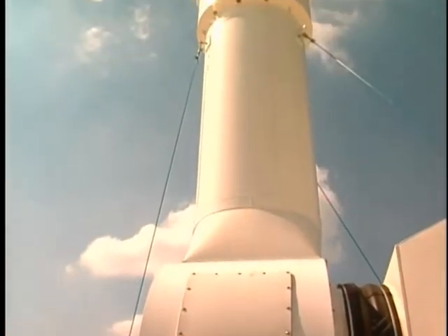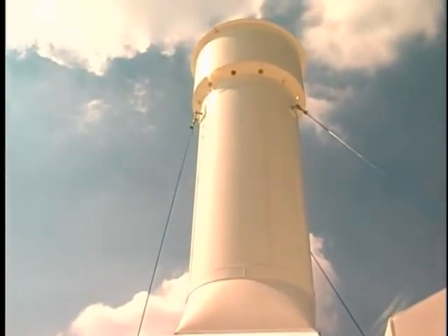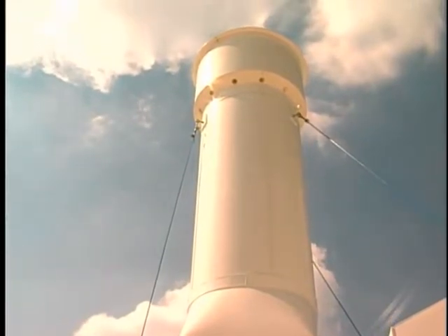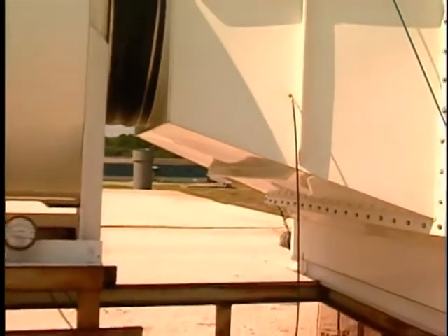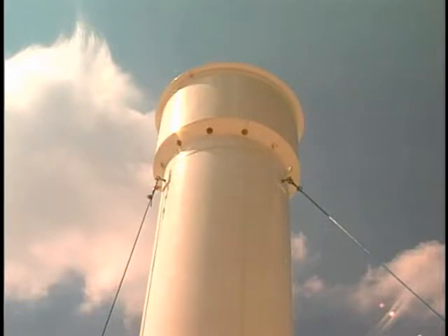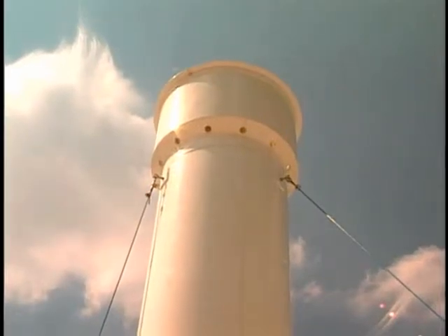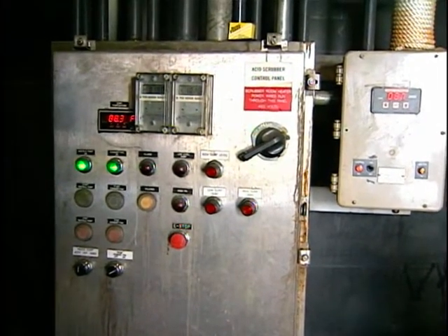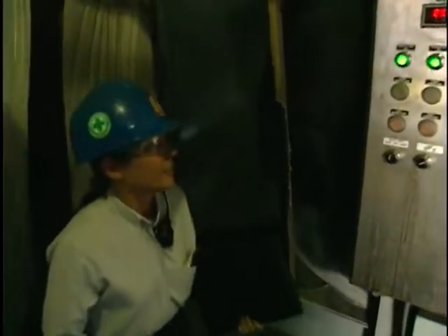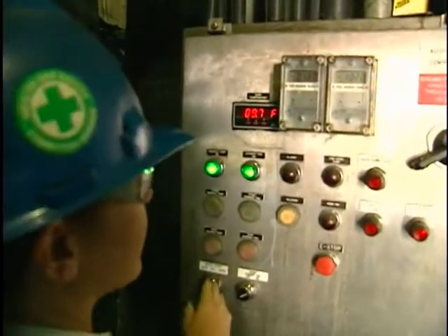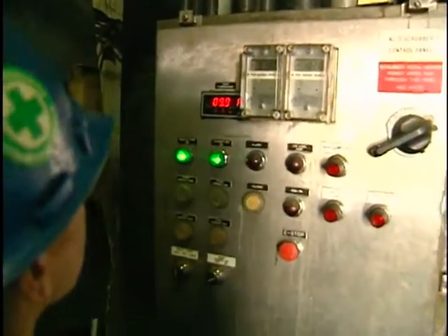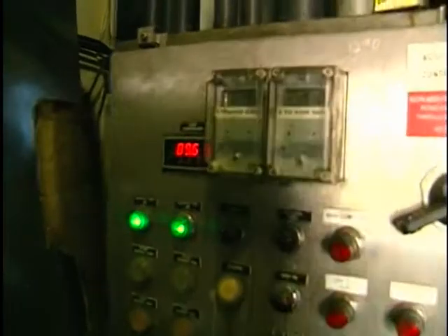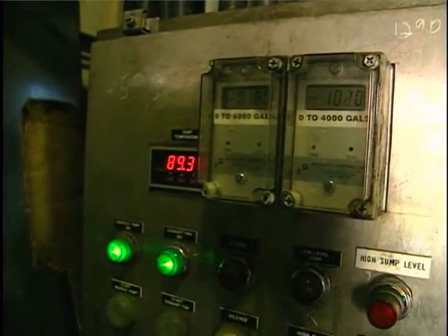The most direct indicator of system performance is the concentration of the contaminant in the outlet gas stream. However, since the gas stream is usually close to saturation at the outlet of the absorber, it is hard to extract a sample and remove the water without also removing some of the contaminant. And in situ analyzers have interference problems on gas streams with high moisture content. Also, commercially available monitors for many of the gaseous contaminants of interest can be expensive. Therefore, less direct indicators of performance are typically used.